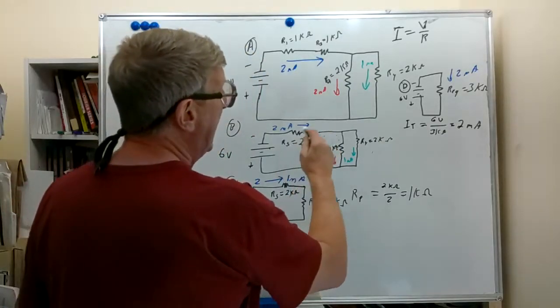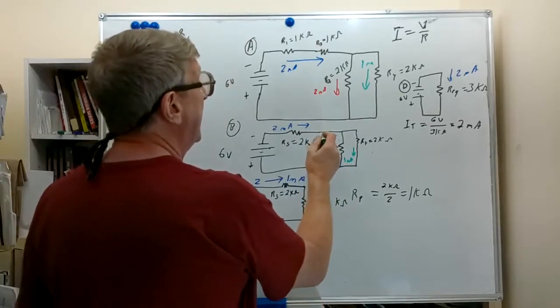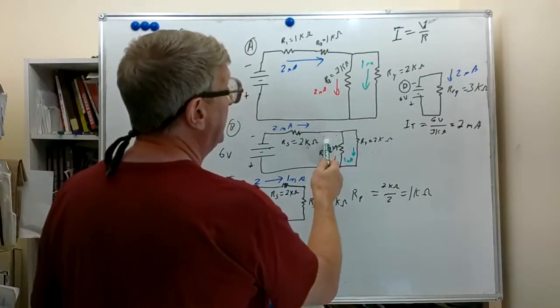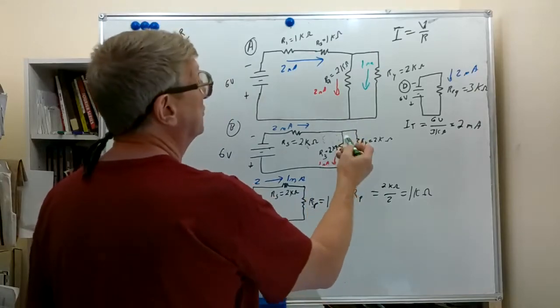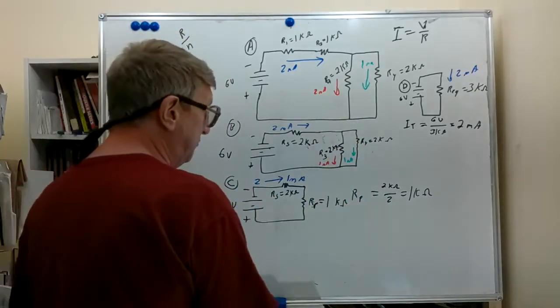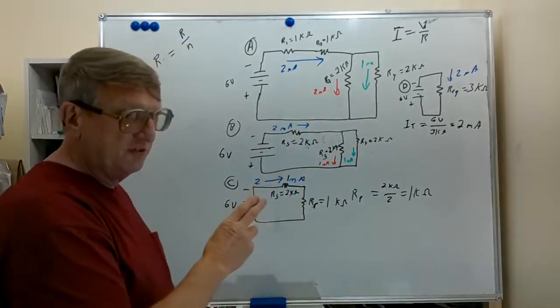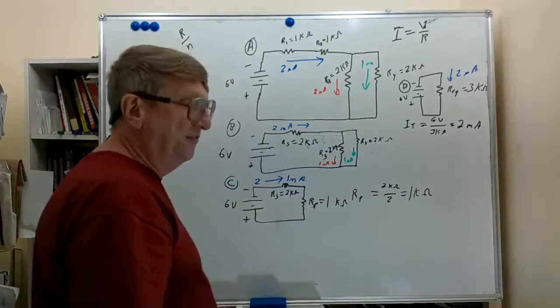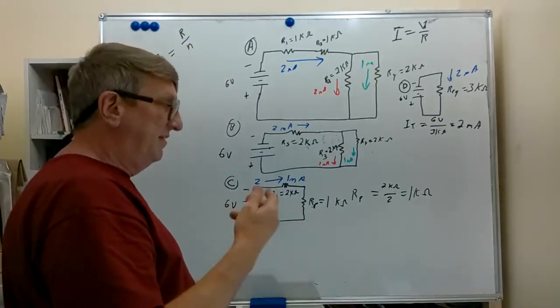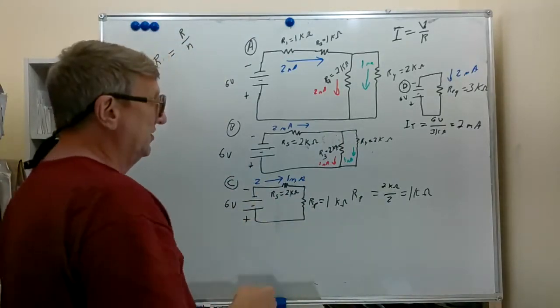but here we didn't have a series circuit all the way. They had to divide, and we saw that they were equal resistances, and what's going to happen with equal resistances, the currents will divide equally, and that's because the voltage across both resistors is the same, and because of Ohm's law, you cannot have the same voltage and the same resistance give two different current values.